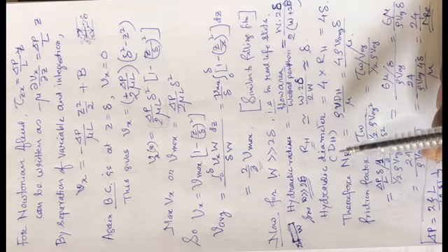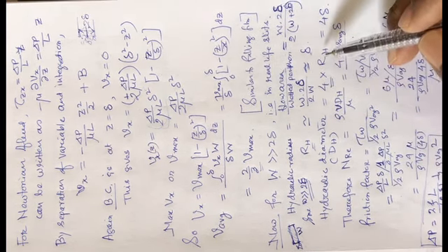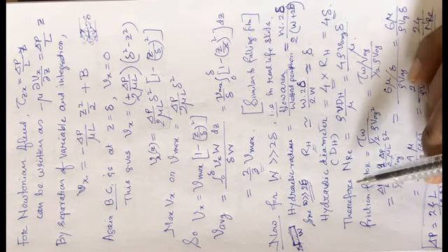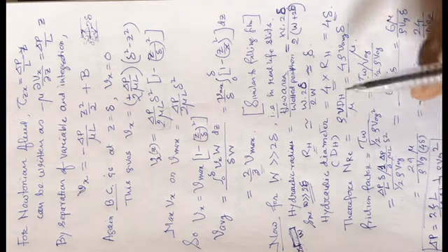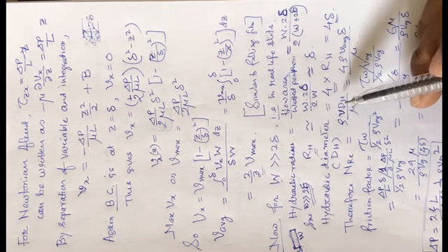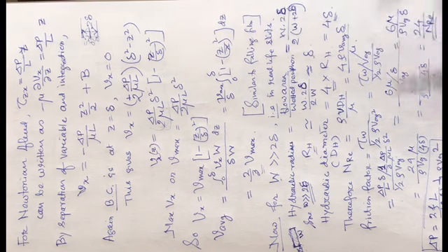Then the hydraulic diameter, you will have to remember this particular factor. The hydraulic diameter is 4 times the hydraulic radius. So it is 4 delta. Therefore, we get that the Reynolds number is equal to rho v dh by mu. Now you see dh is 4 times the half thickness, so 4 times half thickness into rho into V average by mu.